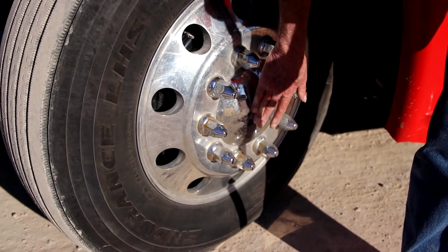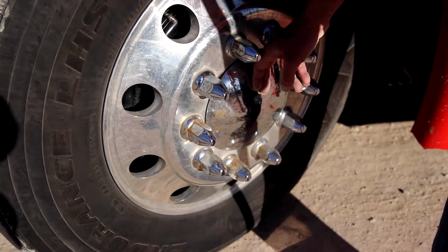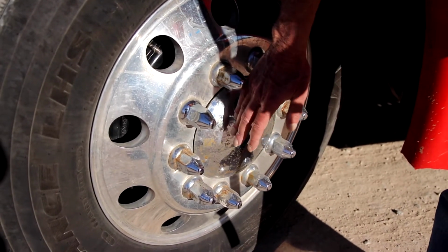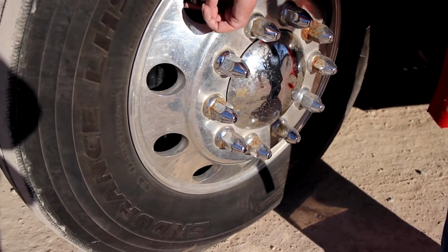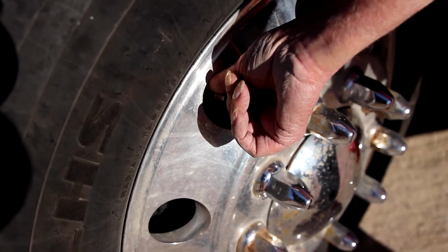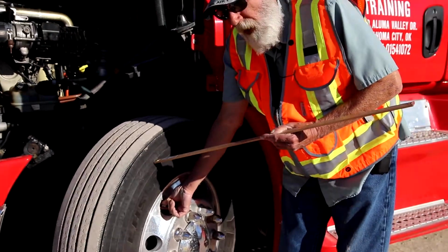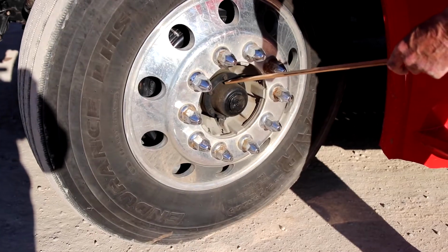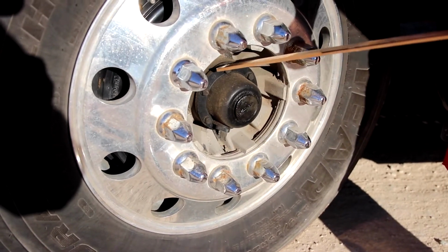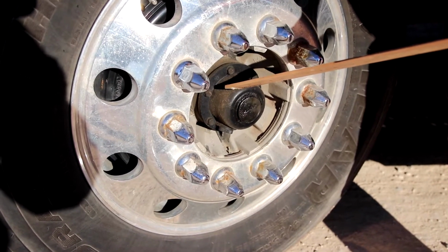And then behind this cover, you have your front hub seal. Make sure that it is filled to factory specifications and it is not leaking. Then you have your tire valve with a cap on it. Make sure that it is securely mounted to the rim and it is not leaking. You must have at least 100 pounds of air pressure in the tire itself. Your front hub seal is mounted securely to the vehicle by bolts, and it should be filled to factory specifications. It does not have any leaks. It's filled with a liquid again.